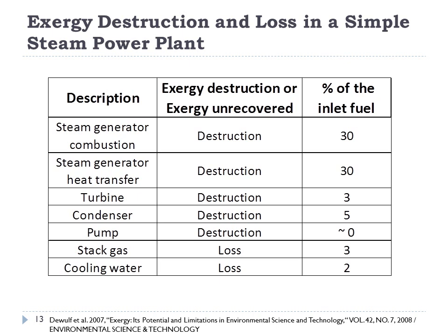So here I just want to give you a feel for what's going on in a coal power plant, where we're combusting coal and using that to boil and then superheat steam, and that's going to be going through a steam turbine. After the steam turbine, it goes to a condenser, so the steam turns into liquid water. It goes to a pump, and then from the pump it goes back into the heat exchanger where it's boiled and then superheated. In the condenser, there's also cooling water used on the other side of the condenser to remove the energy from the steam.